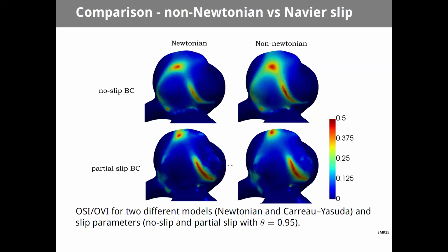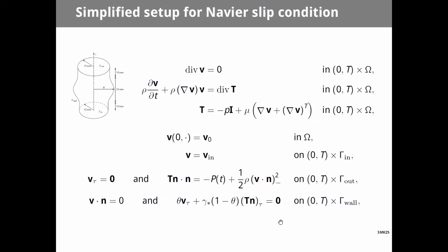So this definitely is some direction where one could explore whether this kind of slip boundary condition can make better predictions than no slip. So going a little bit in detail, if anyone tries to implement the slip boundary condition, it's quite difficult to do.